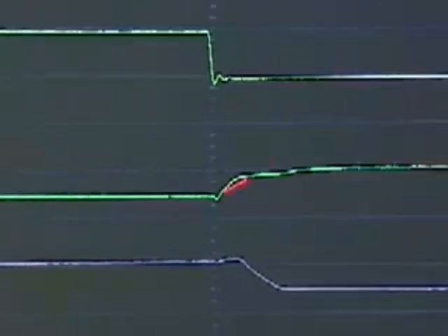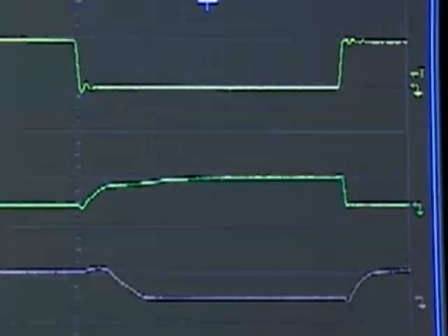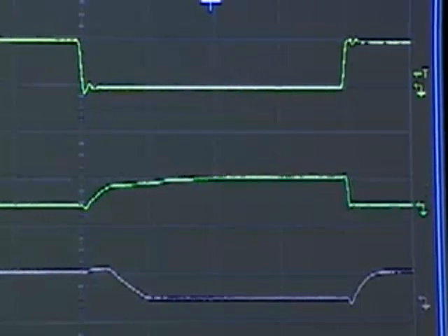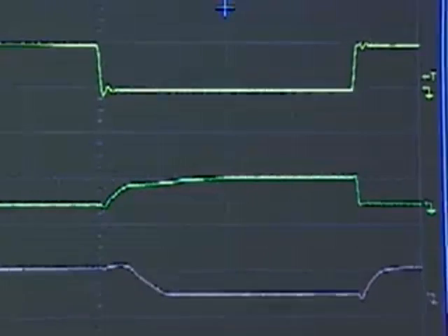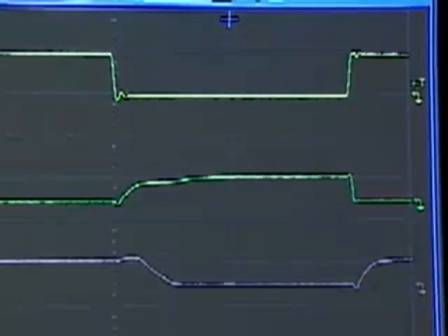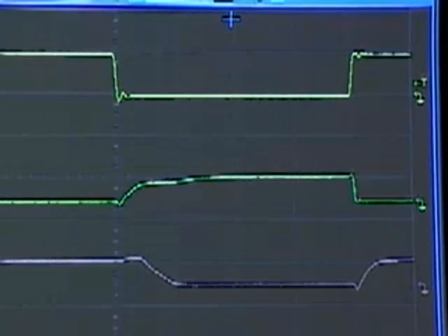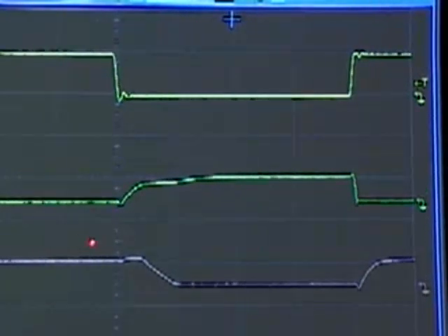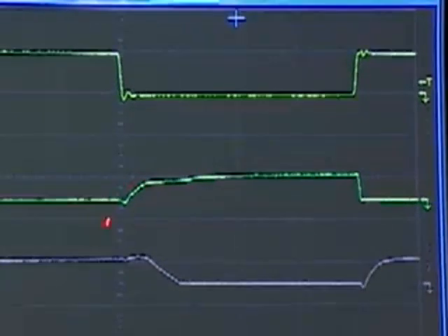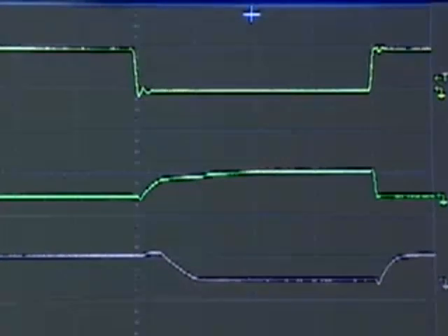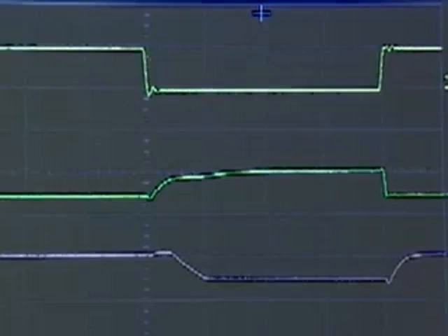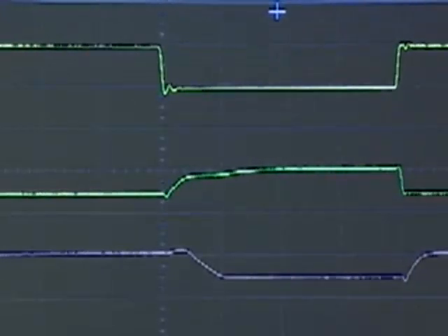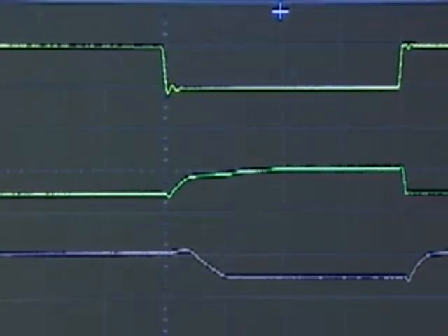There are some other weirdnesses going on here, like a little bump and stuff like that. You can ignore all of that for now. It happens because of certain other very subtle circuit effects called Miller effects and so on that you won't be dealing with in 6002. So focus on this part here. It's pretty slow, and because of that slow rising, I get a very slow transition and some delay in my inverter.